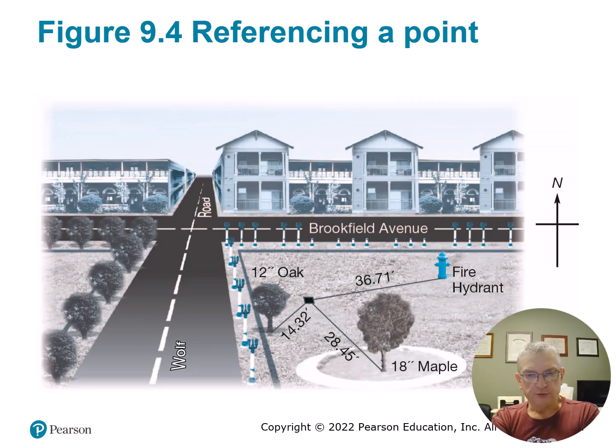So if you're needing to perform a survey and you have to set up a traverse, the first thing you do is you go recon what you need to locate. To include, we tie flagging up over it. This may include taking a machete or a bush axe and trimming understory leaves and branches out of the way so that you can see where everything is. You might do this, might be covered in future courses, if it's a boundary survey, which it most likely would be, to reconnaissance and find some property corners, fences, features that need to be located, etc.